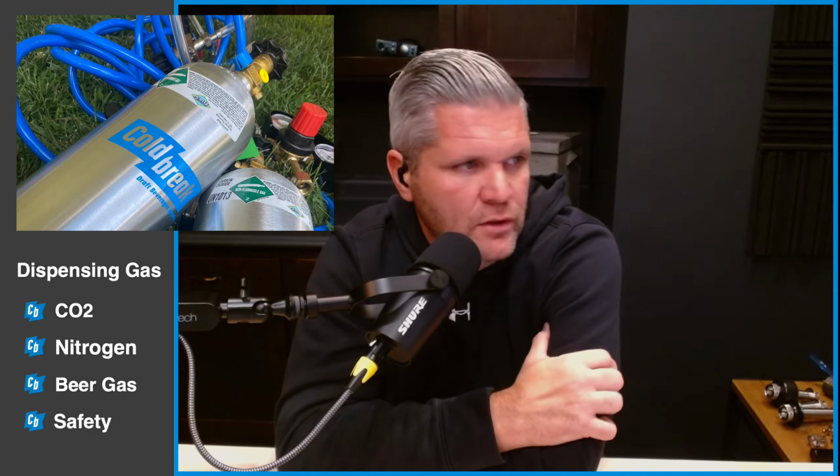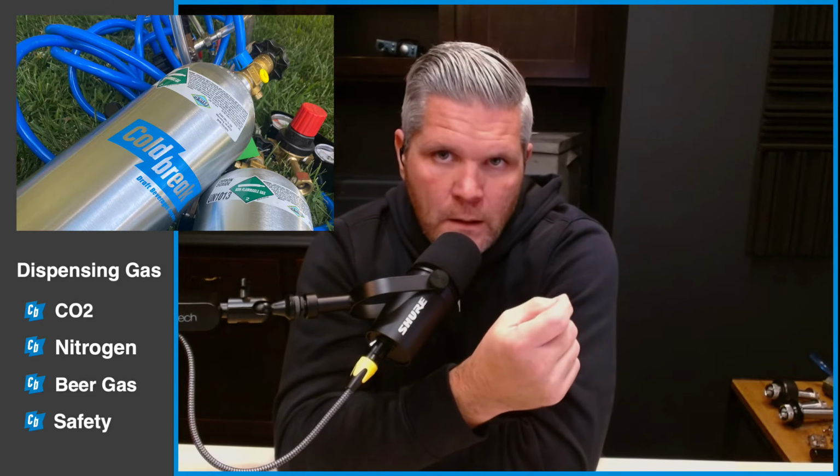The other thing we'll talk about today is safety. CO2, nitrogen, and argon are all heavier than air. So when we're using CO2, especially in enclosed spaces, like a draft trailer, a kegerator, or a keezer, if there's a leak anywhere, it can asphyxiate you. So we just need to be careful. A lot of places will include CO2 monitors, CO2 alarms that will go off in case there's an overabundance of CO2 or nitrogen in the area.